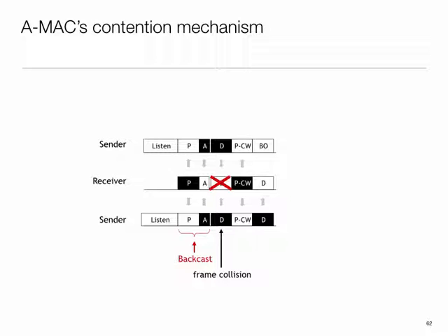Another one is that the probability with which a node will transmit will depend upon how small its ID is. So a node with a higher ID will have a lower probability of transmission. So you stochastically create a situation where it doesn't happen. Now, that's one possibility. Another possibility is that maybe from prior communication, this guy actually does know the IDs. And therefore, it can say, node I, you transmit. So there are different ways of resolving that potential collision.